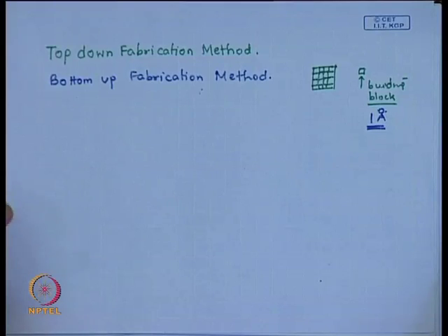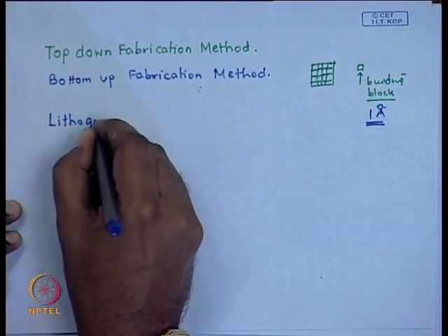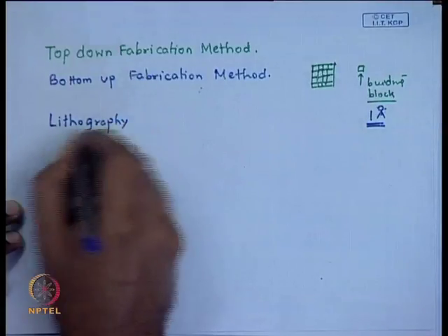Now, the question to ask at this point is what exactly can be self assembly. Photolithography is not a self assembly technique, or not a bottom up fabrication method, and neither are most of the patterning techniques used in the microelectronic industry or in other segments, particularly with polymeric or other soft materials, which fall into the category of lithography. I am coming to the origin of this word, what lithography really means.